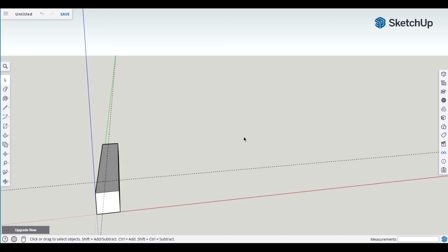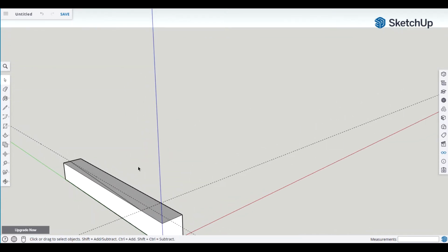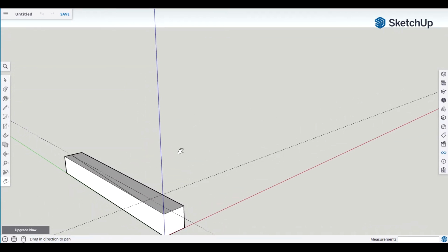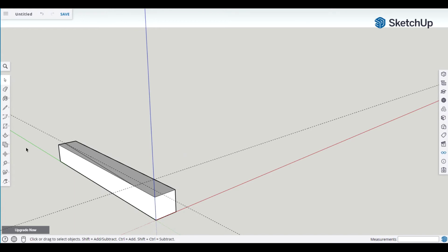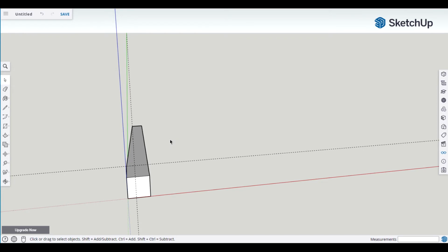We're going to select the line tool, we'll select an L for line. We're going to snap on the intersection, as you can see, and just draw a line and snap there. Space bar, and let's rotate the object. Hit H to bring in a little better view. Next, we want to remove this, so we're going to select P for push pull. Highlight the top, pull it down, click, space bar, and then we are done with that taper.